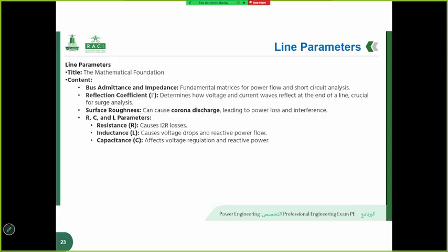The Z-bus matrix represents the network impedance, which is a measure of the opposition to current flow. It is the inverse of the Y-bus matrix and is primarily used for short circuit analysis, which helps engineers calculate the magnitude of fault currents.